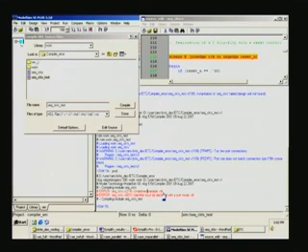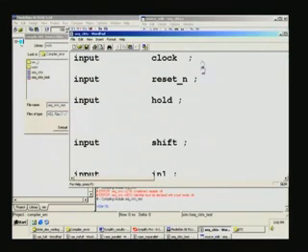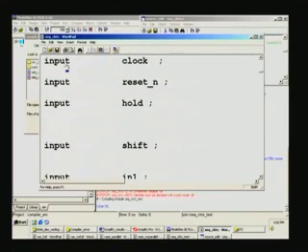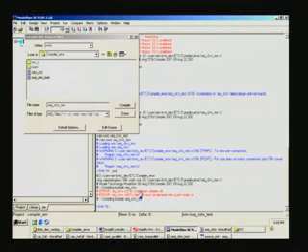I changed the name right at the input as CLOCK, so that means CLK is undefined. So we had to declare the input. This follows from that, and that is what the error is here.